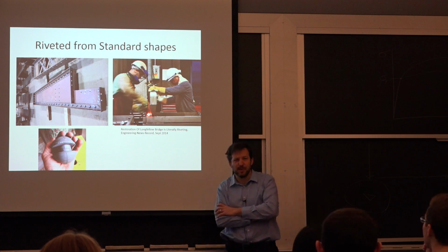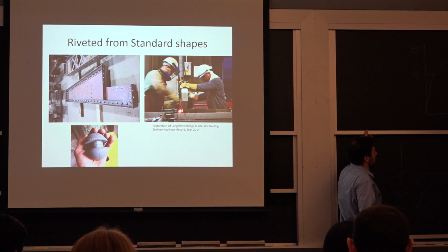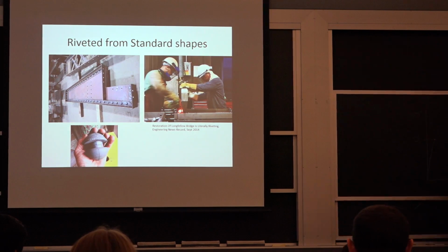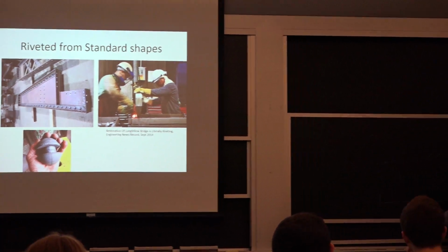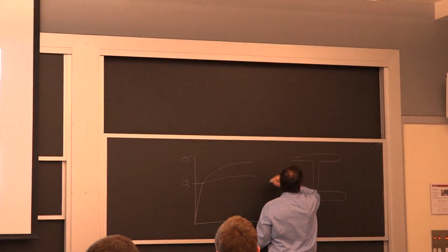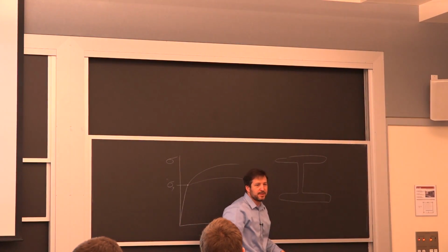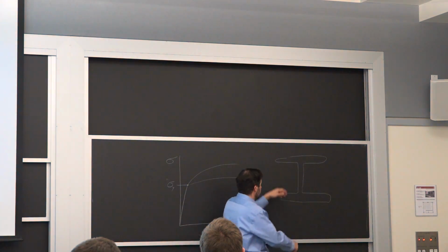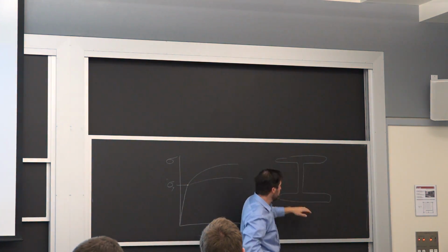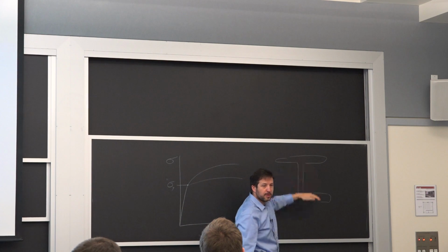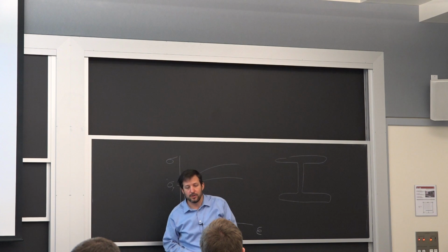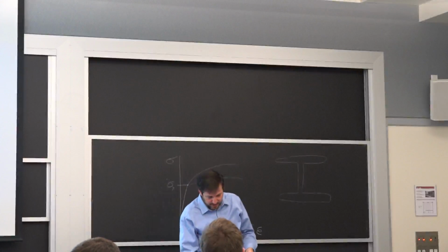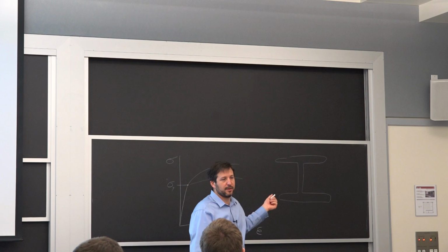They didn't know how to do I-beams, so in modern days, a lot of the construction uses a design like this, a single piece that's formed, and I'll bring one to the class that's done different ways. This is a single piece of steel. It's great in bending. If you apply the load this way over a length, you have a lot more material in the fiber than in the center, so it's efficient in terms of the weight and the cost. So they couldn't do that back then.